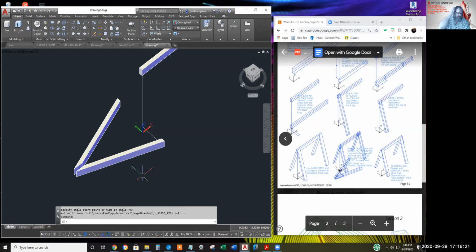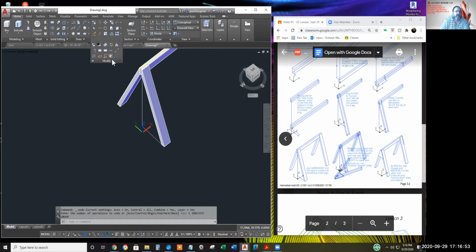The old way, it asks you to specify 2 points on the axis you want to rotate about. And it'll swing toward you or away from you whether you pick point 1 first or point 2 first, in accordance to the right-hand rule. You interested in that, or am I fire hosing you with too much? Let me show you the old way. I can't remember if there's an icon for it or not. Since there is no icon for it, I guess it's more reason to ignore it.